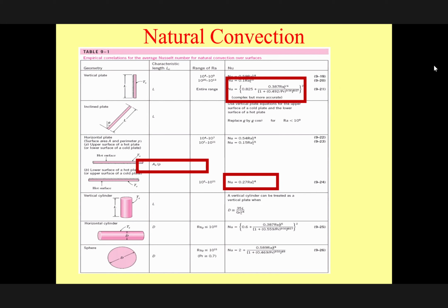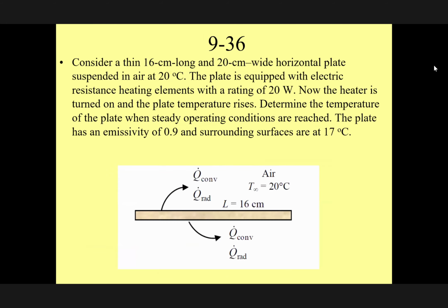Now let's go back. I'm sorry, let me go back again. Now, there was one question one gentleman asked at the beginning of the class. It mentioned now, I have to assume a temperature for the plate. You are right, because you have to calculate Rayleigh number. In order to calculate Rayleigh number, you need the temperature difference between the plate and air.